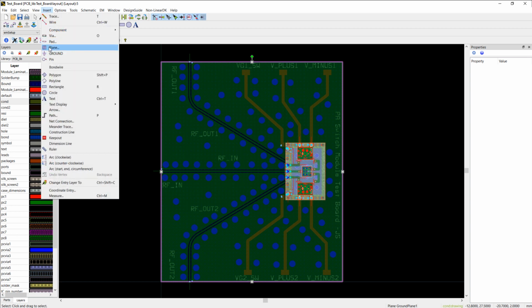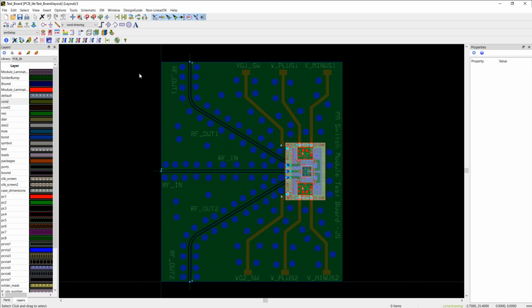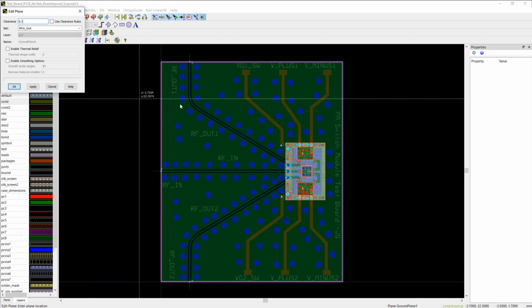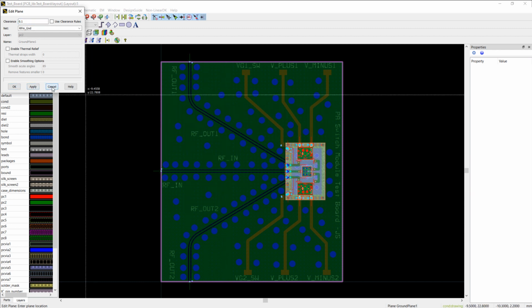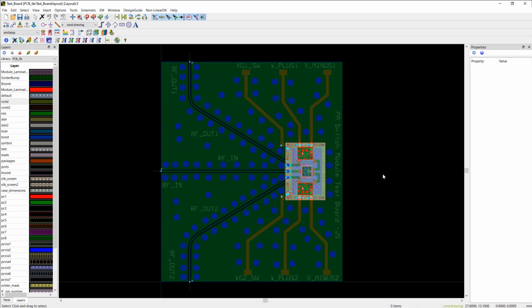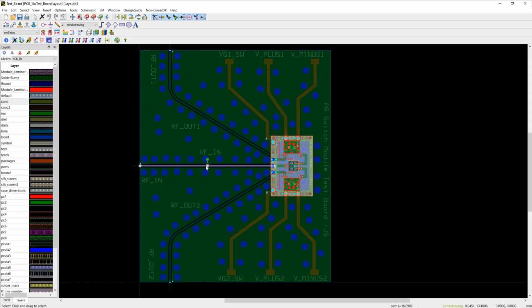You see, I constructed that ground plane, and once I have the ground plane, I double click on it and you can see the clearance is 0.1 millimeter on the top. Later, I will show you how I can verify this good 50 ohm line impedance using RF Pro's user-defined analysis, which focuses and runs EM analysis only on one part of the structure, namely the RF lines here.